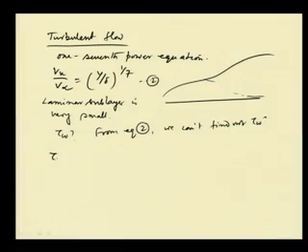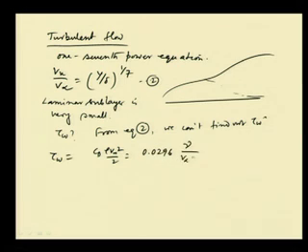So, in case of turbulent flow analysis, we have to take an expression for tau w. Let tau w be taken as C d into rho V infinity square by 2, which equals 0.0296 into nu by V infinity x whole to the power 1 by 5 into rho V infinity square.